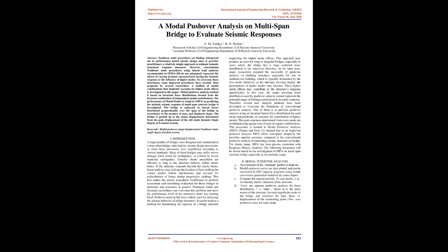Modal pushover analysis method is based on invariant force distributions formed from the factored combination of independent modal contributions. The performance of modal pushover analysis, MPA, in predicting the inelastic seismic response of multi-span concrete bridges is investigated. The bridge is subjected to lateral forces distributed proportionally over the span of the bridge in accordance to the product of mass and displaced shape. The bridge is pushed up to the target displacement determined from the peak displacement of the nth mode inelastic single degree of freedom system. Keywords: modal pushover, target displacement, nonlinear static, single degree of freedom system.